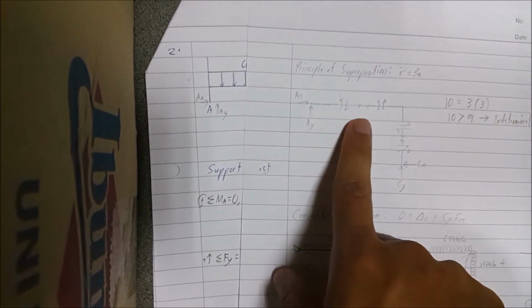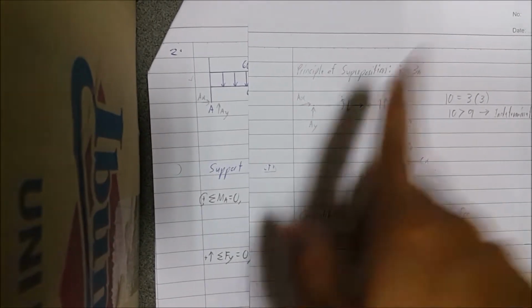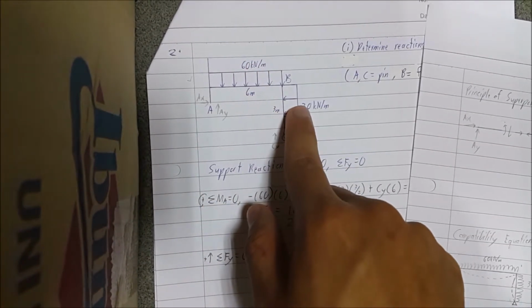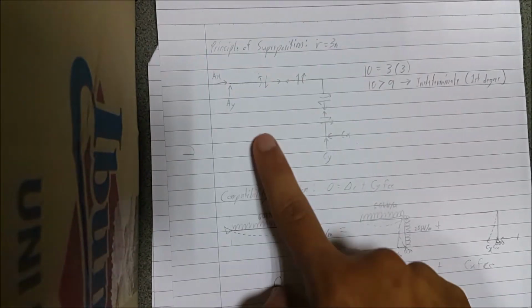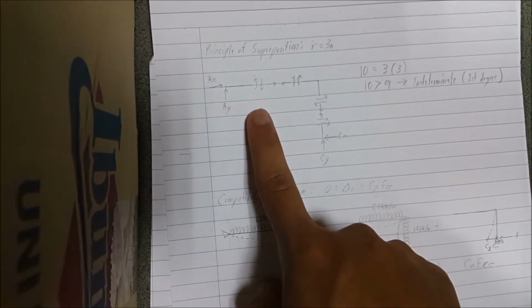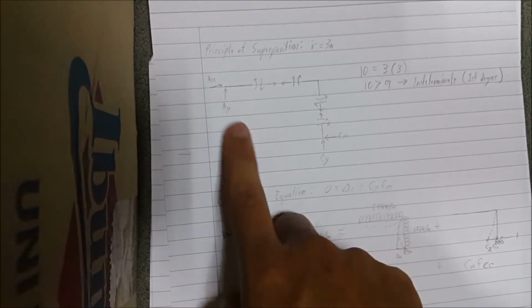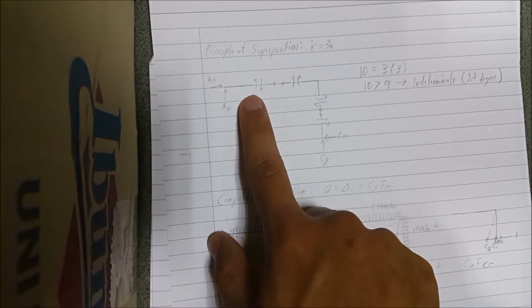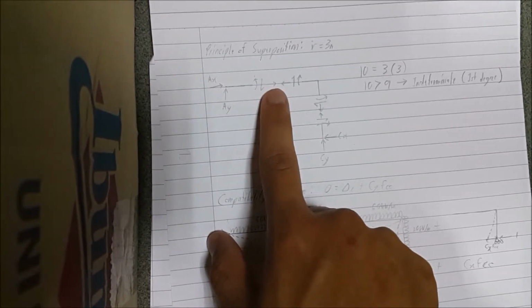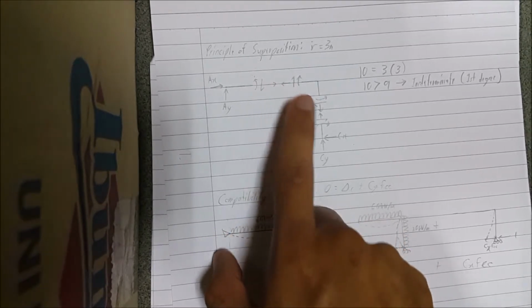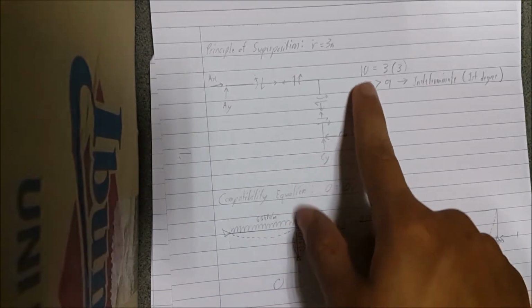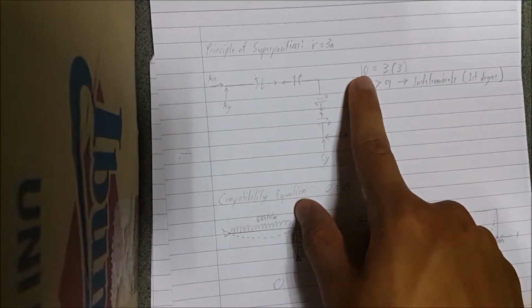Because this is a frame, we are going to have to cut at some points. We have to cut the diagram at 2 places, mainly here and here. So we end up with 3 parts, as I've drawn here. From here, we identified the forces: 2 forces at A, 3 forces here, because this is a counterbalance, the equation of equilibrium, another 3 forces here, and 2 forces at C. That's how we get altogether 10 unknown reactions.